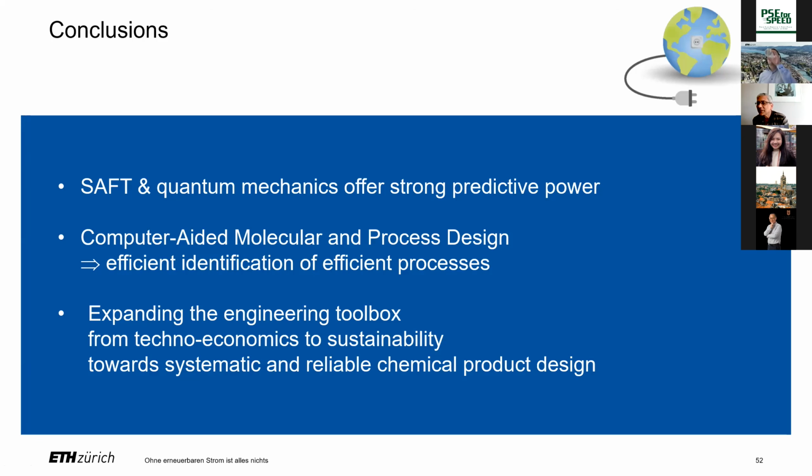So there is one question here, actually several. The first question is from Alejandro Pedroso. Is it possible to integrate an organic Rankine cycle in a plant to supply cooling utilities near 0 degrees using the condenser at the end of the turbine? Yes, you can do sub-atmospheric cooling, if you have a demand for this. Yeah, this can be done. It would lead then to other conditions.